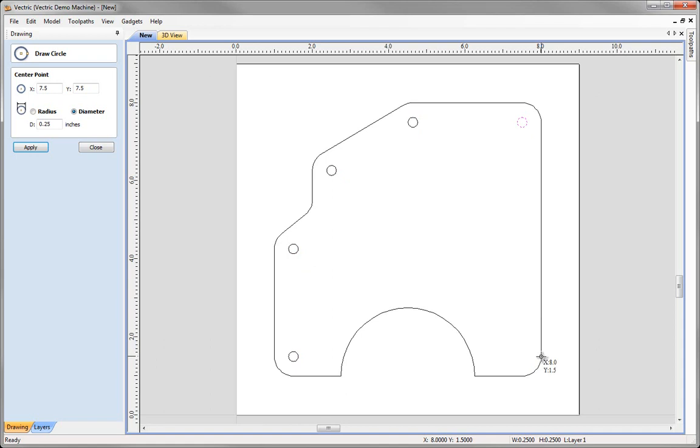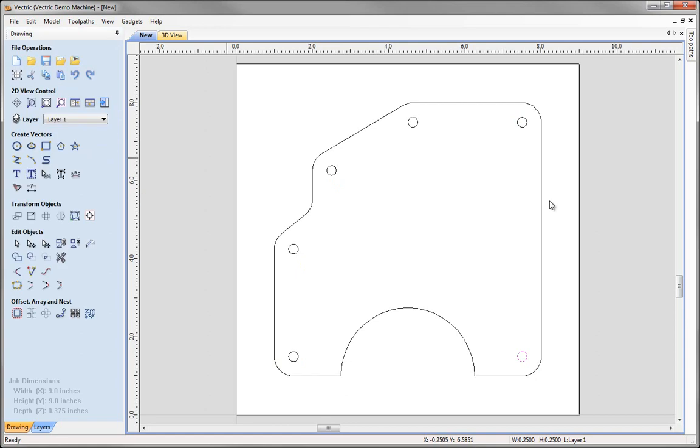and sometimes you may need to kind of hunt around for it. If you need help, you could always look for the edge of the fillets here and kind of work up from there to find the center point. And again, once you get the crosshairs, you click and that's going to create that vector in there. So we've been able to very quickly snap those circles into those positions based on the center point of that external arc that we created with the fillet tool. So let's just close that now.